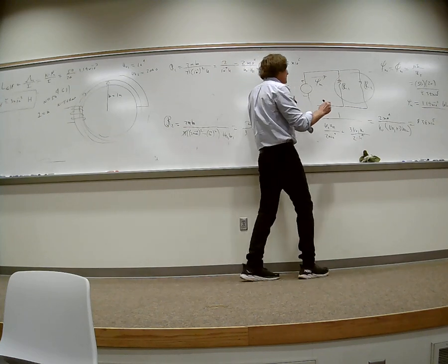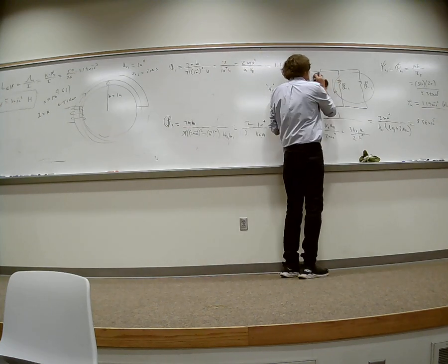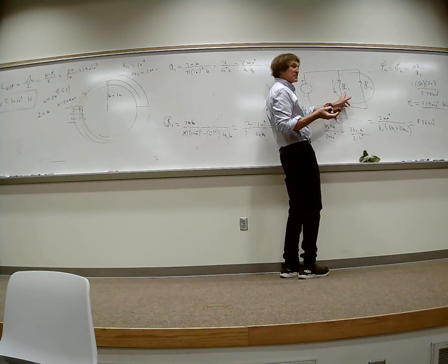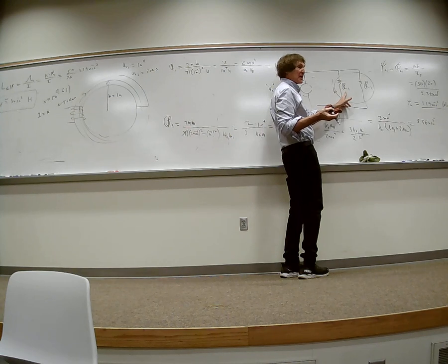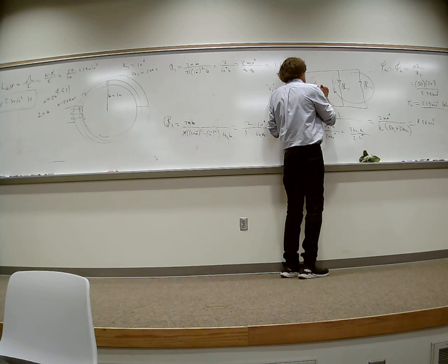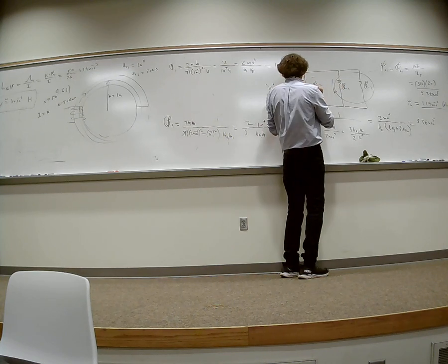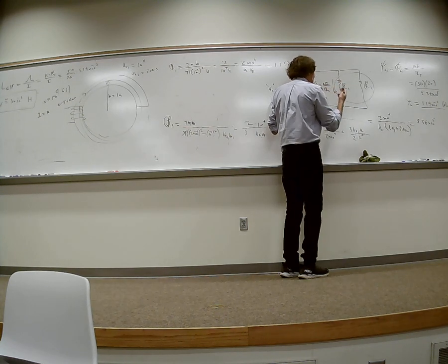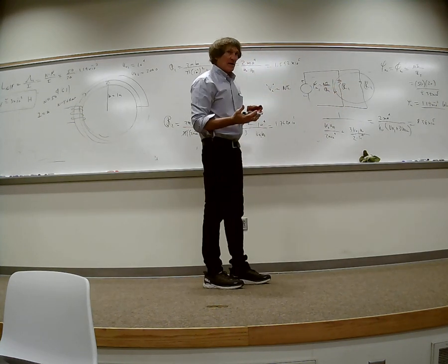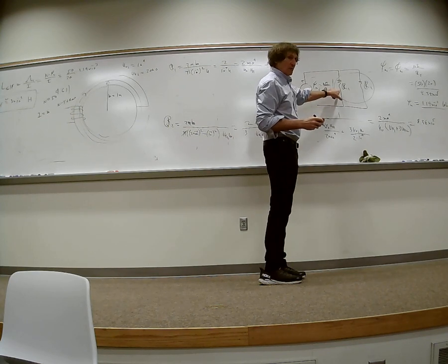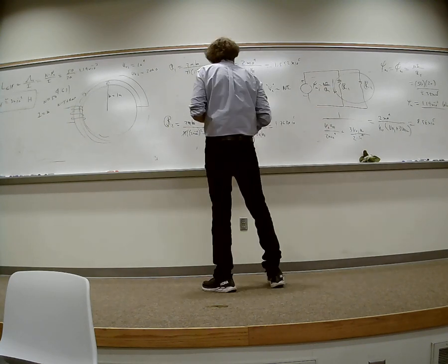If we wanted the current flowing here, just down here, we would take the voltage divided by the resistance if it was an electric circuits problem, right? Here, you just take the magnetic voltage, or I'm just going to put it this way. Magnetic flux in 1 is simply going to be Ni divided by the reluctance 1. That would be in Webers. Then we divide it by the cross-sectional area to get the value of the B field. Remember, this is in Webers, B field is in Webers per meter squared. So just bear with me here.